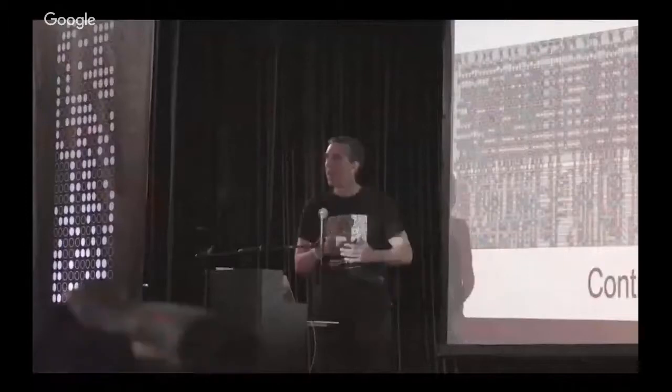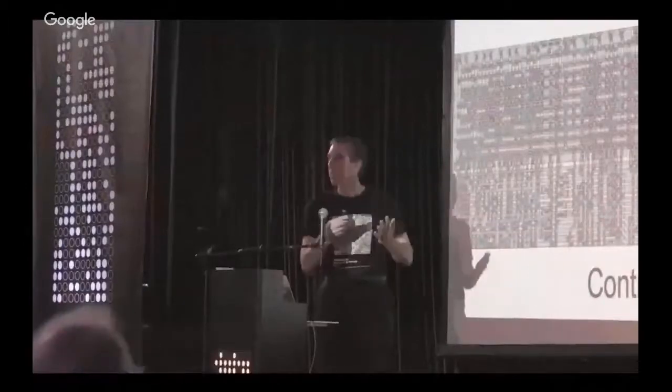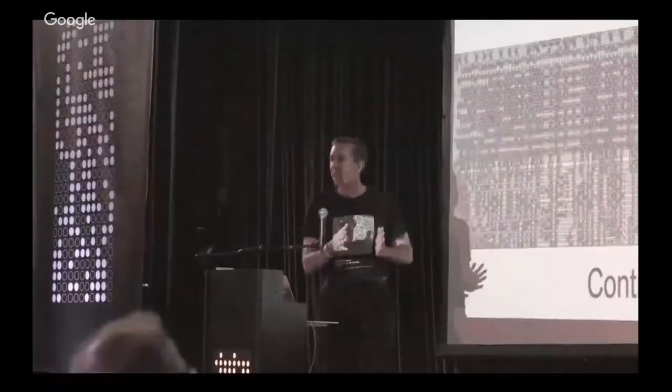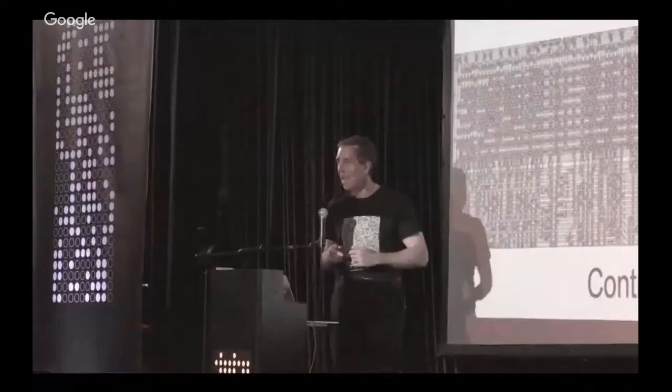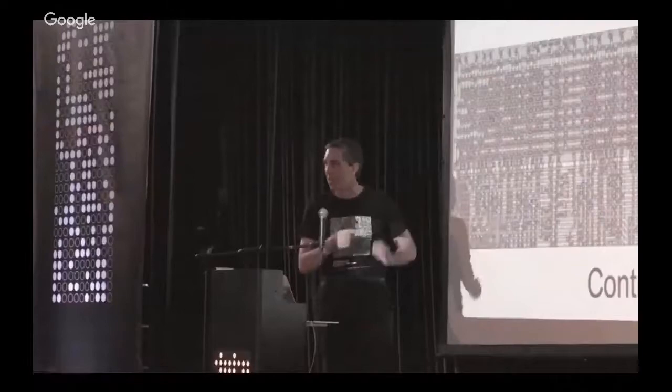Other things will match all the different instructions. So this is where the matching between the instruction set and what actually happens in the chip happens. And so instruction sets get designed so that it's easy to get from a bit pattern into what's happening.